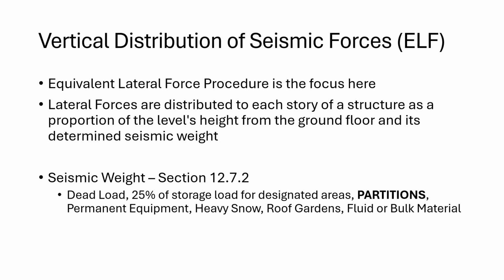And what does that mean? So the seismic weight of your structure is determined by section 12.7.2 of ASCE 7. This can be the dead load of the structure. You're going to include all of that. 20% of storage load for designated areas.